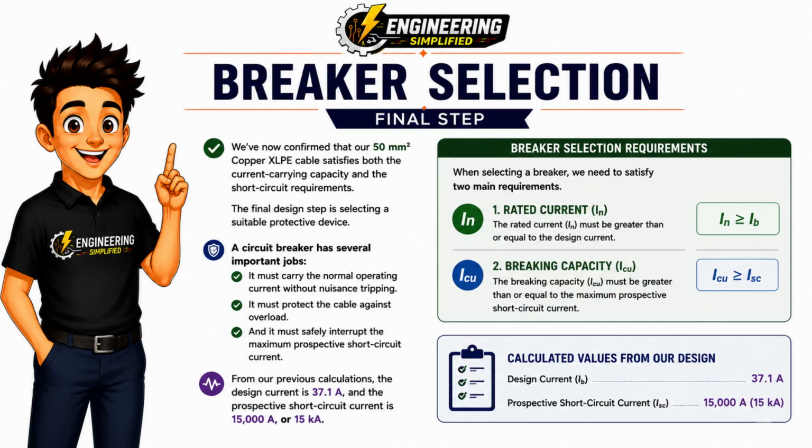A circuit breaker has several important jobs. It must carry the normal operating current without nuisance tripping. It must protect the cable against overload, and it must safely interrupt the maximum prospective short circuit current. From our previous calculations, the design current is 37.1 amps, and the prospective short circuit current is 15,000 amps, or 15 kiloamps. When selecting a breaker, we need to satisfy two main requirements.